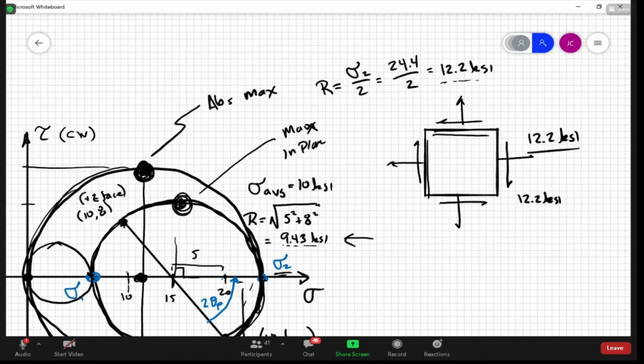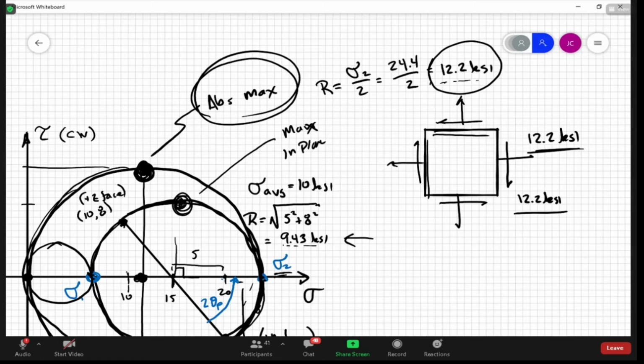Now, when you ask for this max absolute shear stress, or when the book asks for it, or I ask it on an exam, again, because the geometric rotations are a little bit complicated, we usually won't ask you to display it, but this is what the components would be. It does have a shear and a normal component, right? But this is the answer we're going to be looking for: the maximum absolute value, the maximum absolute shear stress, okay? All right.